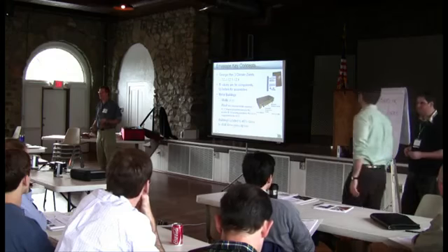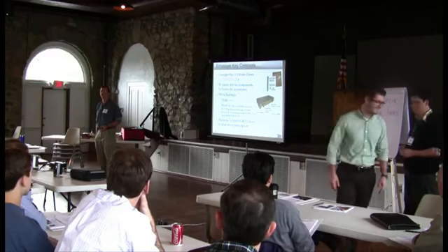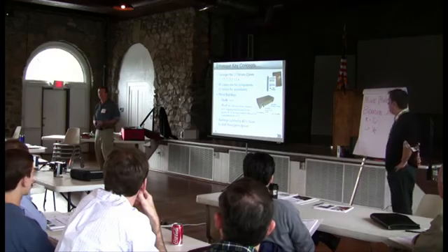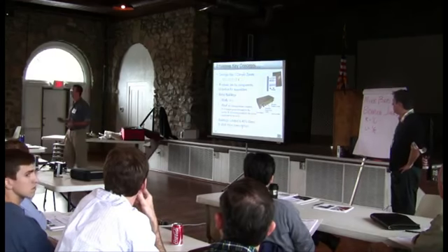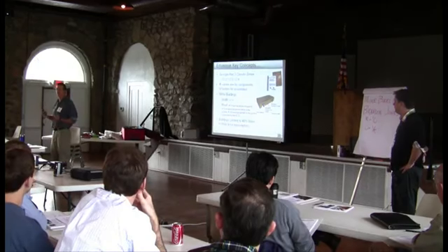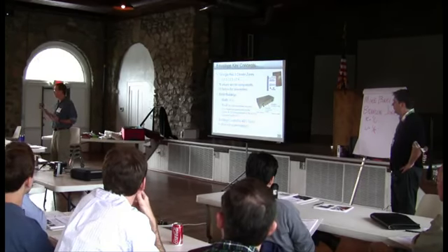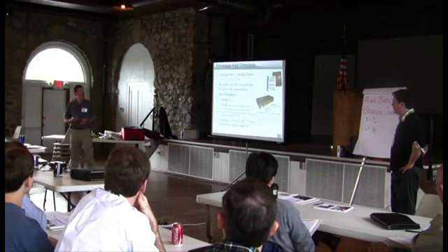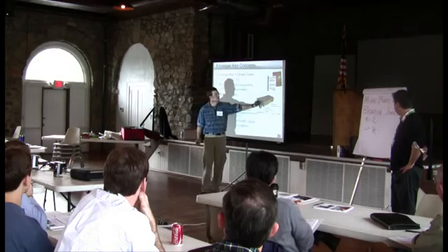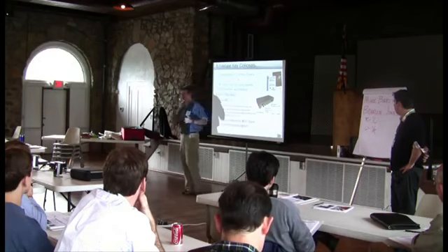And they're probably not that big a deal at the end of the day, because if you think about it, a metal building does have some compression of the fiberglass. Where do you see the fiberglass getting compressed in a metal building? At the purlins, right? And the code does have some requirements that you have to have thermal blocks to minimize this conduction effect.